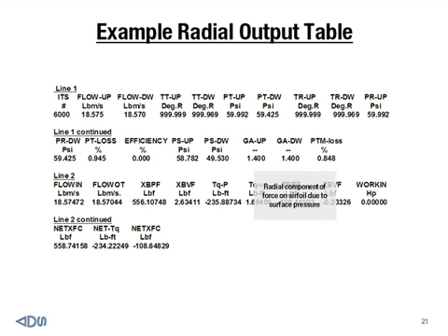And the radial forces on the airfoil due to surface pressure. Typically these forces are small and are not picked up in component calculations of mean line and streamline, but because of the detail of 3D CFD they are picked up.